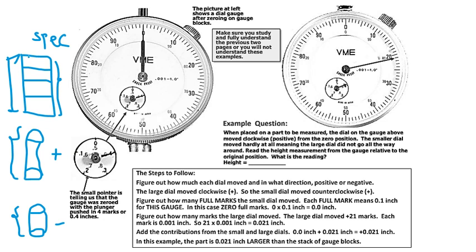Because you definitely know the exact measurement of this, because your gauge has values on each of the blocks. All you have to do is sum it up. So you're going to have a sum of this, and you can add the reading, and you get the height of the larger item. If your pointer is shown on the negative side, you're going to subtract what you just read out of this sum, so you're going to have a shorter height, or a smaller item.